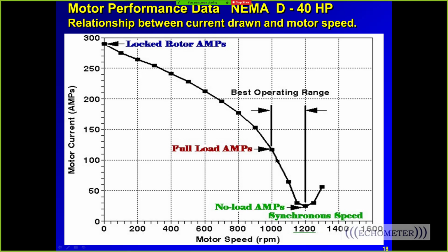But as long as the RMS use of current during the stroke doesn't stay above the motor rating for amps for heating, then the motor cools back off, and then it goes back on the downstroke, and so it kind of operates this way: upstroke and then downstroke, kind of like that. And the speed's changing all the time throughout the stroke.